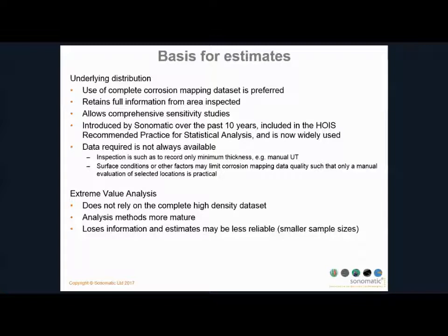HOIS, for those of you who aren't aware, is a joint industry project which includes participation from many of the major oil and gas operator companies, as well as inspection and integrity related vendor companies. So that approach is included in the recommended practice, and it is now widely used in practice for making estimates in the case of sampling inspection.